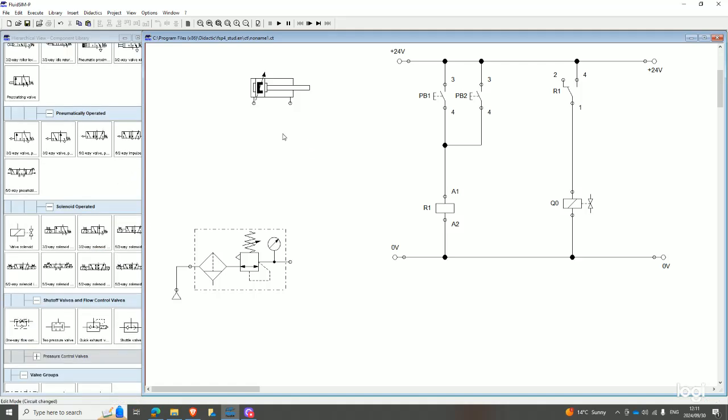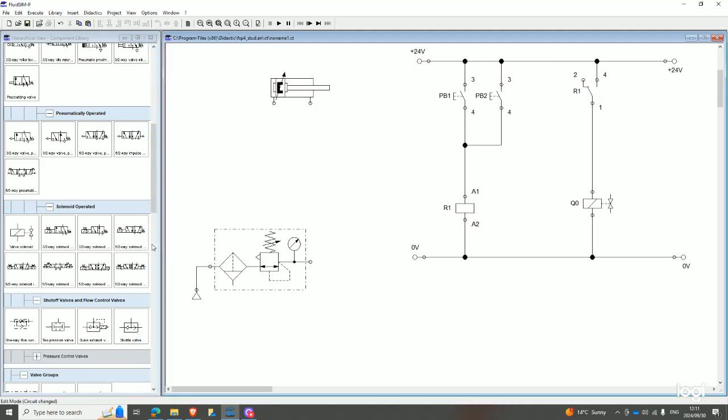So now, as I said, if you still remember, for you to be able to control a double acting cylinder, you need a 5-way, right? So the trick here is selecting the proper 5-way, right? So here, if I use this 5-way, since there's a spring load at the end, the cylinder won't stay in the advanced end position, right? Therefore, and one other thing, we can't use this 5-way solenoid operated valve, because we need two push buttons, one to advance and one to retract, right? So the appropriate valve would be the bistable 5-way solenoid operated valve, right?